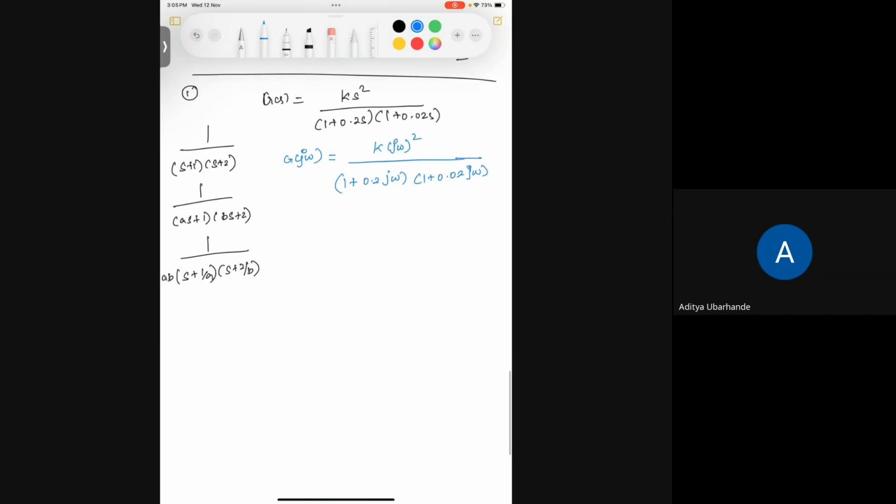The next thing is, ultimately in our Bode plot, we won't draw any curves, right? We don't know how the curves will be, but asymptotically we try to approximate it. So we will have something like this, some changes in the plot, but from one frequency to another frequency, it will be constant. For example, this is one frequency, second, third, fourth, some omega c1, omega c2, I would call. So we are trying to find the magnitude at this frequency and the slope until it reaches the second frequency. These are the two different attempts we are making.